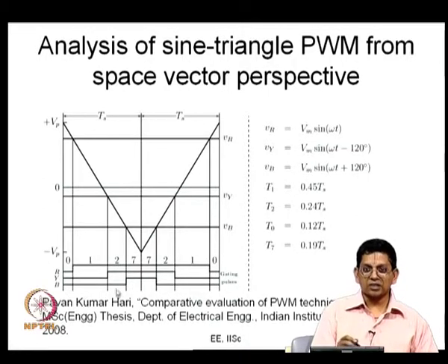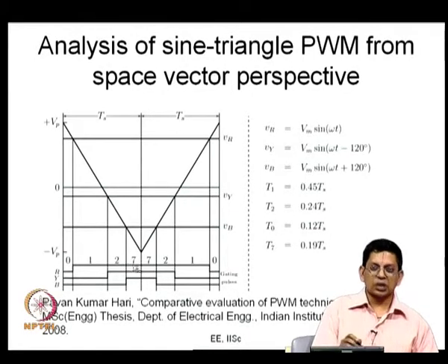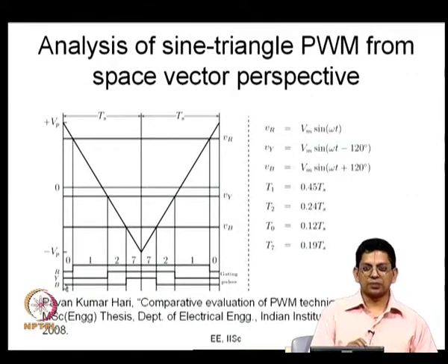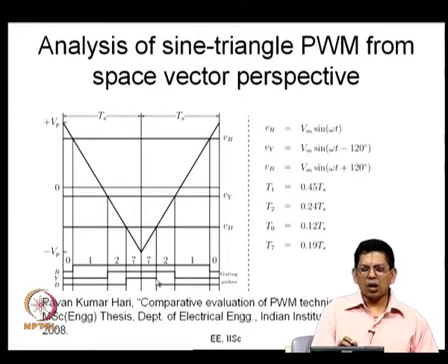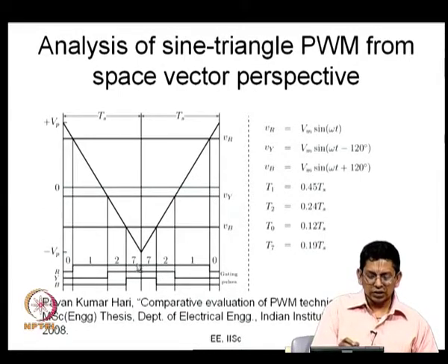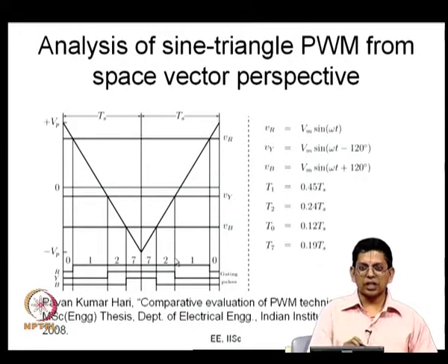I will be making this statement again and again, please bear with me, but it is very important for us to realize. When you add these common mode components, T0 and T7 change, but their sum does not change. Now, T7 is a little longer than T0. So what you should do here is add a small negative common mode voltage to all 3, such that T7 reduces and T0 increases and both of them become equal. This is what you can see from this illustrative example, and we can do this quantitatively.